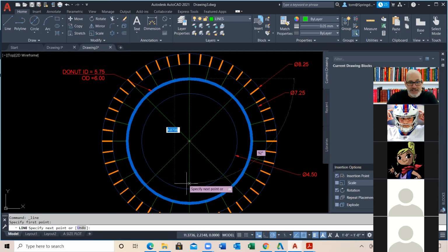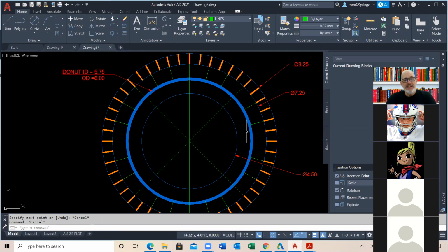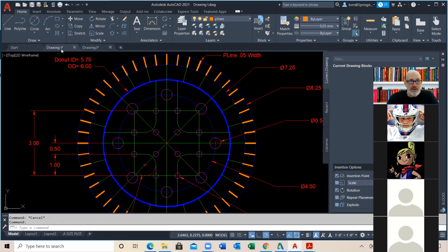And as I'm doing this right now, it's really starting to come together. It's starting to look like something. All right, so go to here, and then we got that. Now, the next thing I've got is I then have this issue where I've actually got these lines here that are offset. So I got this line here, all right? I got this line here. All right, and it tells me right here what the distance is. It's 0.5. So it's 0.5 to get these other green lines in. So that means I need to offset these lines 0.5 away to get those others, 0.5.